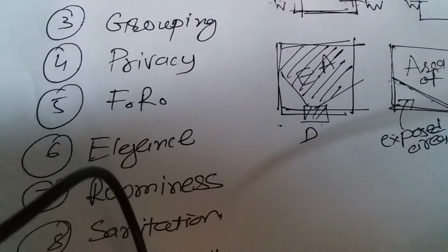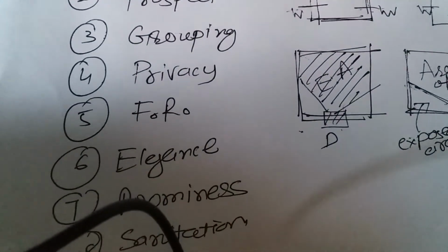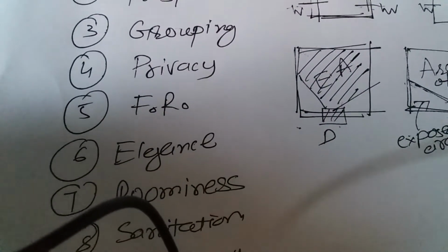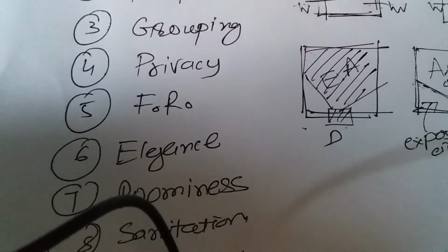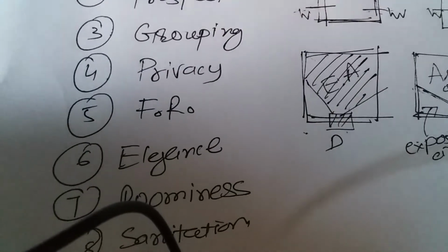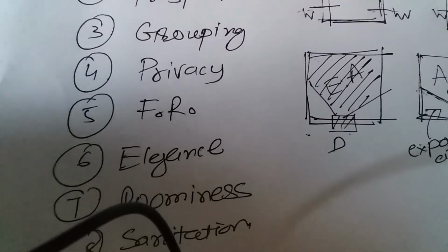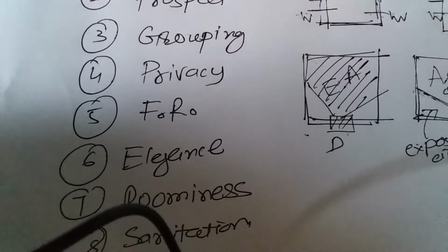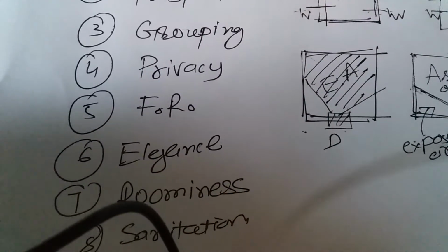So generally a domestic building shall have a front yard of at least 3 meter width, or a minimum of 4.5 meter from the center line of the street. In case of a building, 4.5 meter minimum wide space should be left open in front of the building and should form an inspectable part of the site. Every room intended for human habitation shall be exposed to an interior and exterior open air space of the width or dimension of an open veranda.